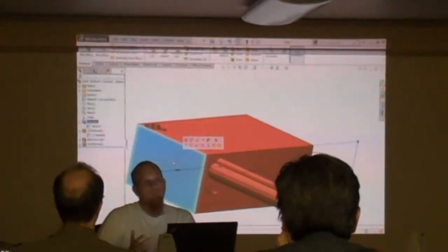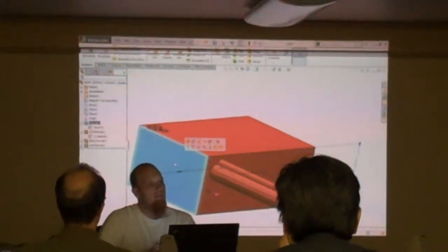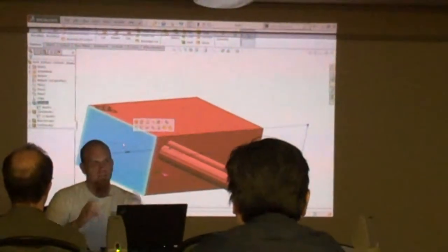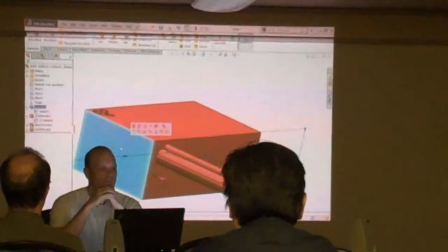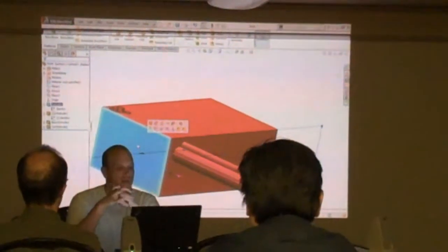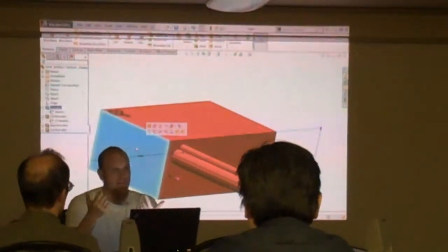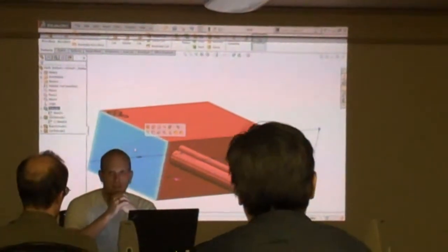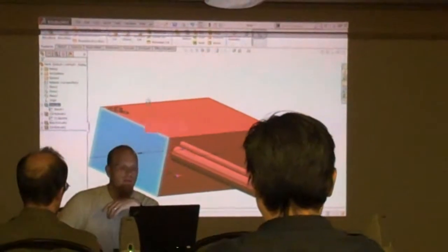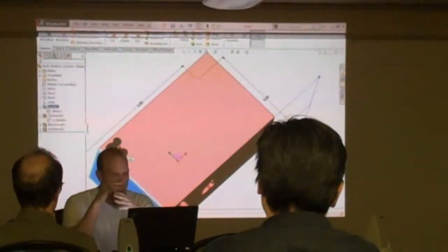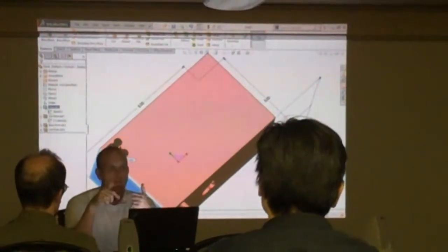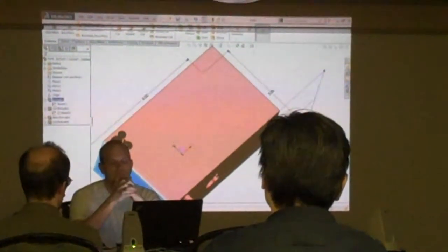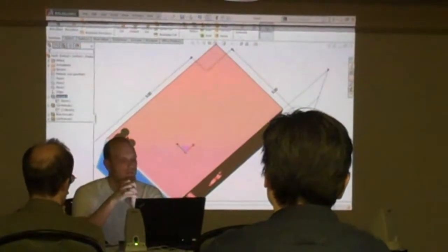Yeah, if you know for sure it's going to be a hole, it's never going to turn into a slot possibly, or whatever geometry. It could be a square shape or any shape in the world, splines included. If I use convert and I add geometry to the original, then that next sketch is going to fail, especially like what I did here with putting the ears on it. I have to go in, redo it, and deal with the failing edges and handles.